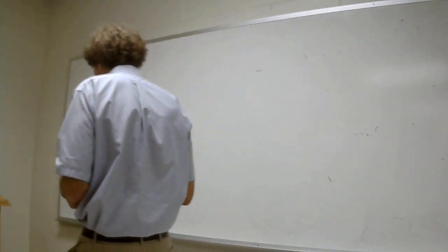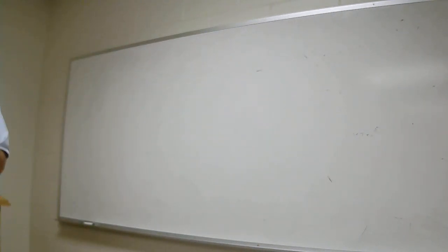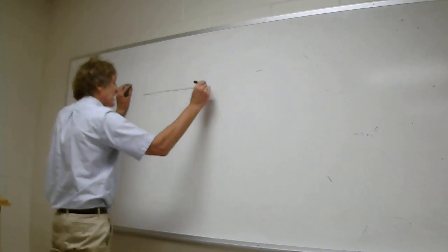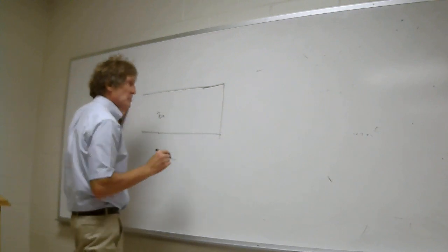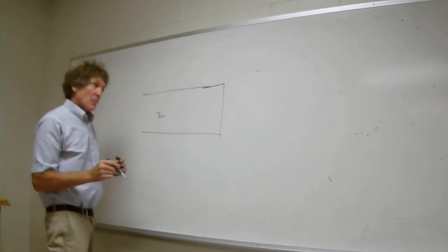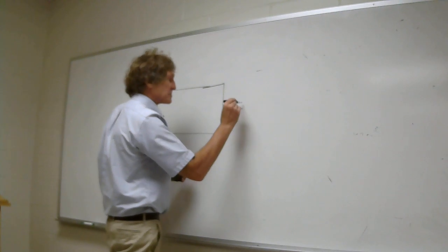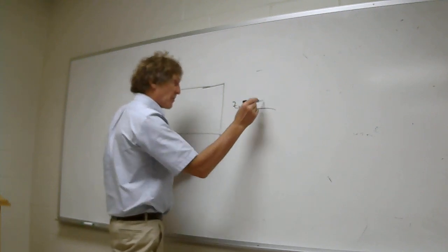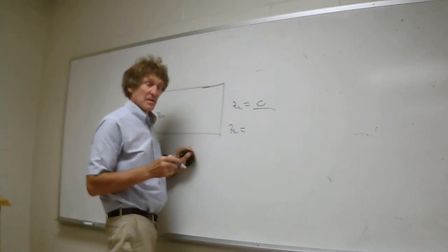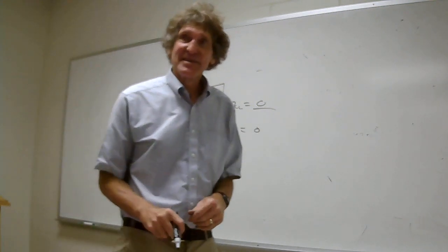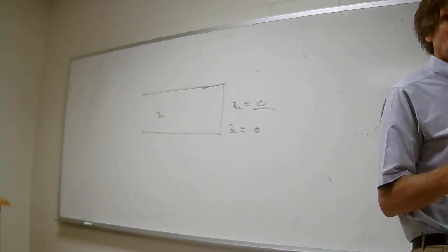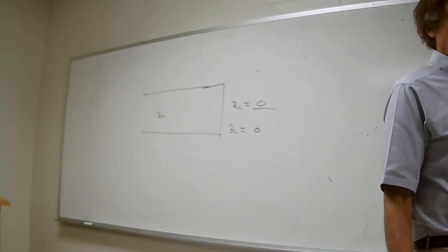Remember, we just care about impedances that are plus or minus j something. Y'all with me? So just follow me on this. If you have a standard transmission line, characteristic impedance Z naught, and I put a short circuit on it for a load, what is ZL for a short circuit? Zero. What's the normalized value? Zero. People, stop. It's a trick question. Zero divided by anything, still zero, if the anything has any value other than zero.